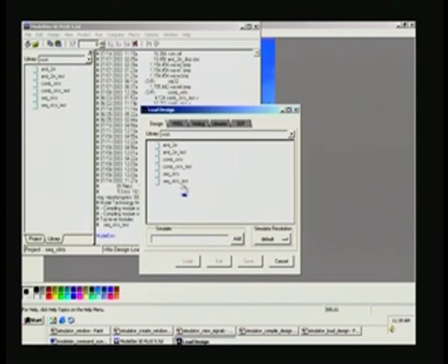In this, you will see sequential circuits test, there is no .v. Earlier I pointed out that it was pointing to the top module as sequential_circuits_test, which is what is listed here, and mind you it is in the work directory. Let us see what happens here. We double click once again; you can also make a single click, in which case the same thing will be copied here, and then say add, and this load will light up. A shortcut is to double click here straight away, so that you can dispense with pressing add.